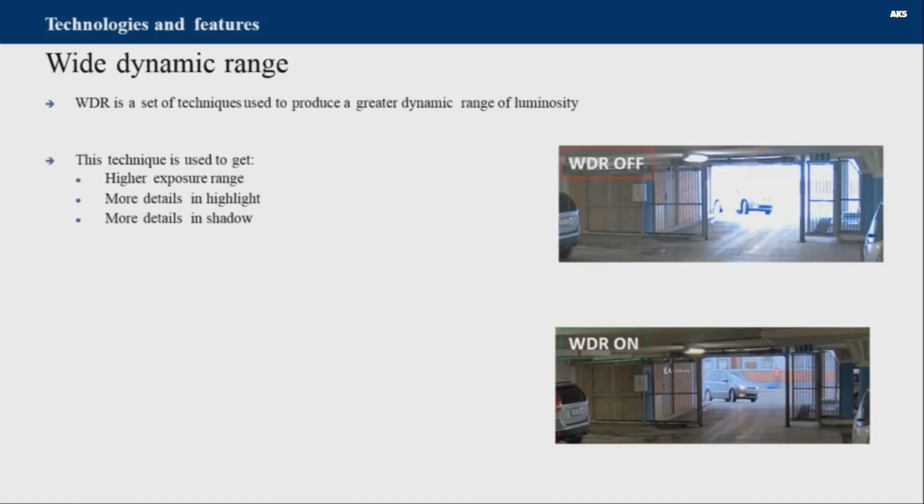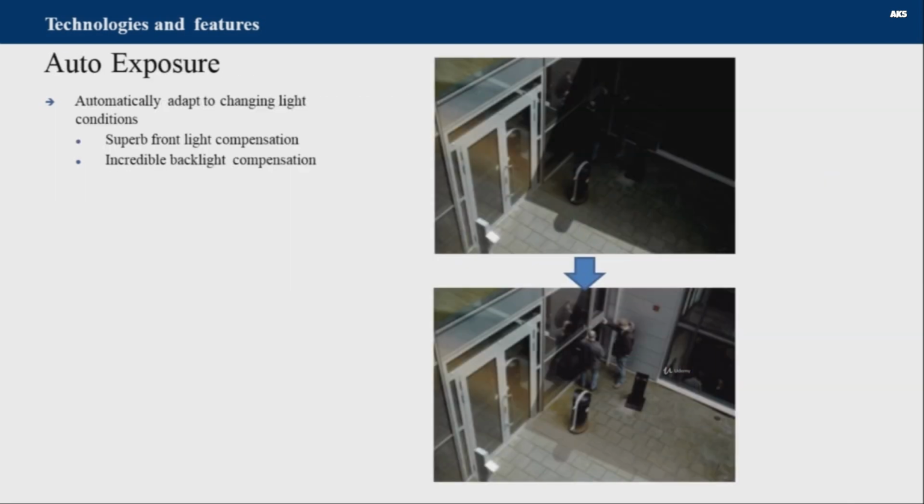Next, we have wide dynamic range. So, WDR mode is a technology that extends the camera's range to cover a greater span between the bright and the dark areas in the image. Typically, the camera will produce an image where objects in the dark area will hardly be visible. So, wide dynamic range solves this by applying techniques such as using different exposures for different objects in a scene to enable objects in both bright and dark areas to be visible. For better performance in low light conditions, the automatic exposure automatically detects the light level and maintains a clear picture if this mode is activated.